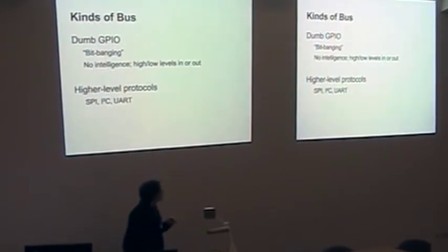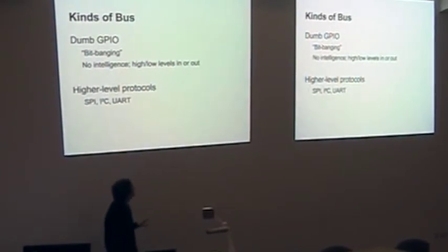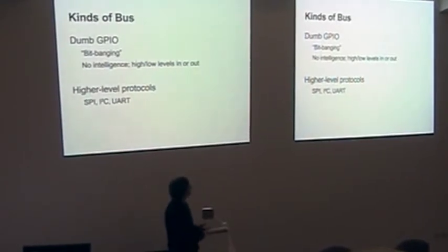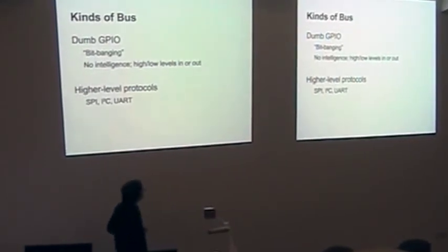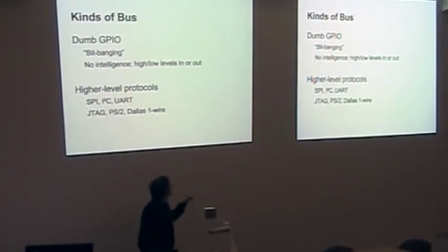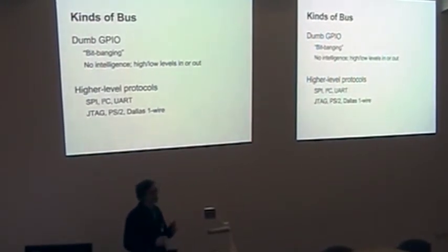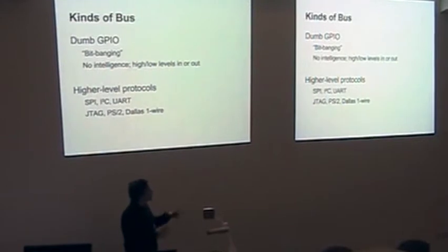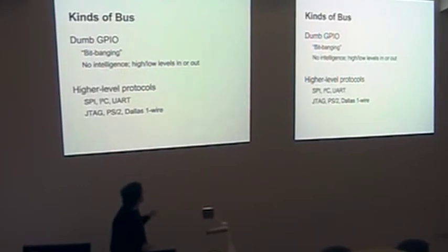I will go into those. The thing will also act as a serial port, which is of dubious use given that you connect it through serial anyway. So you sort of have a USB attached serial machine that can do many things, including be a serial port. So I don't quite know why they put that on, but sometimes it's useful. The thing itself will also talk a number of other protocols, JTAG, which is more of a hardware debugging protocol that a lot of fancier microcontrollers and CPUs will talk so that you can do very strange debugging things with them. That's quite universal and powerful. I'm not going to get into that one.